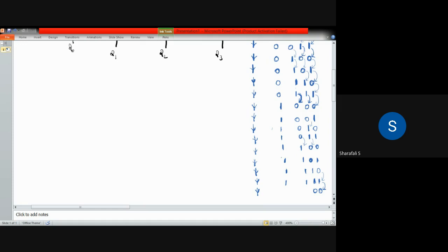And because of this 1 to 0 transition, it is at the negative edge again. So the second flip flop also provides the negative edge to the third flip flop as the clock pulse, so that this one is going to change to 0 again, and this will also give a negative edge to the fourth flip flop, so that the Q3 value also will be toggled to 0.